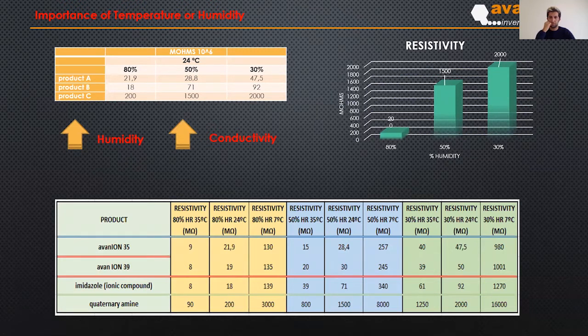Then you send the sample to Germany, to winter Germany, where the temperature is 7 degrees. The sample has been outside of your facility for 2 or 3 days, and you are going to make the measurement in Germany at, I don't know, 10 degrees because it's inside, or 9 degrees, and, I don't know, 30% humidity. The value that you get could even be outside of the measurement range, more than 1000 megaohms.